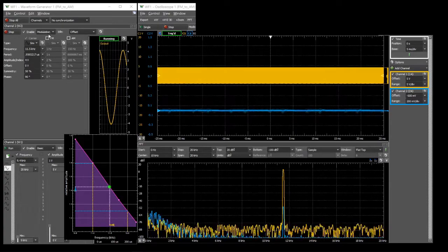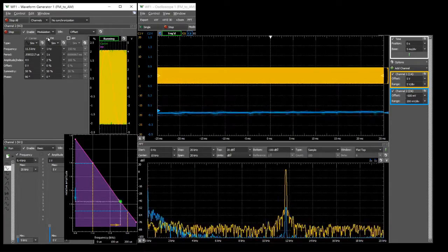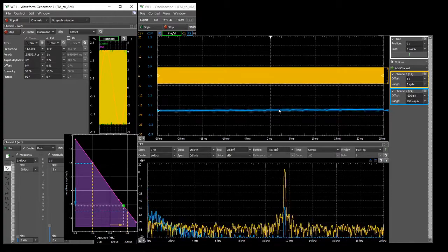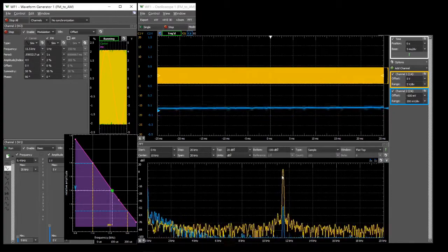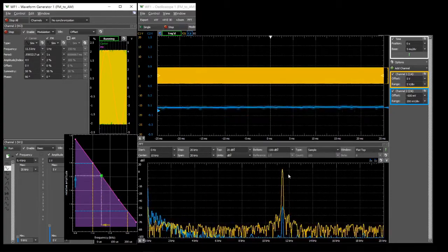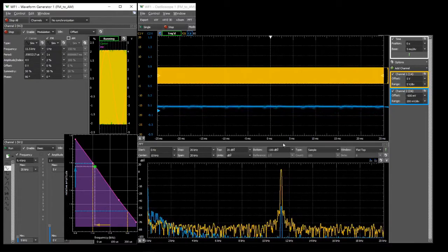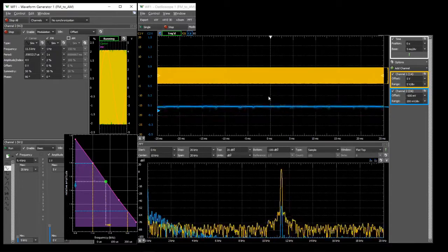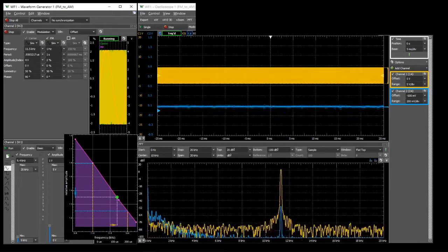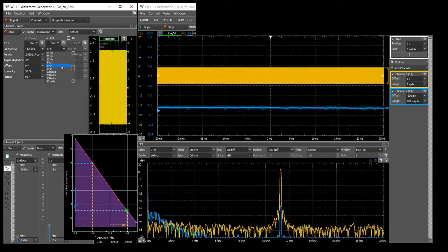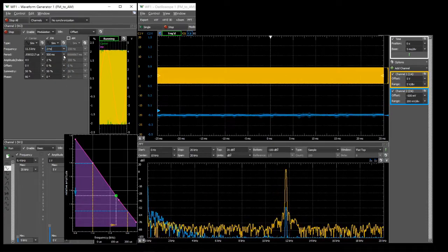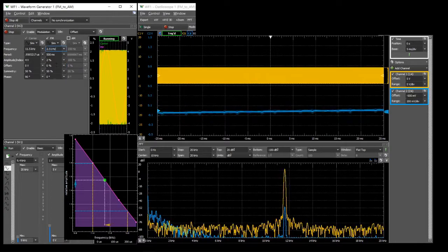As illustrated in the animation graphics on the lower left, the carrier output amplitude, the blue trace, moves up and down correspondingly to the Fourier spectral line moving side to side. How fast the modulation should be is determined by the data rate. In the following, observe the modulation rate being slowly increased, and the effect on the Fourier spectrum.